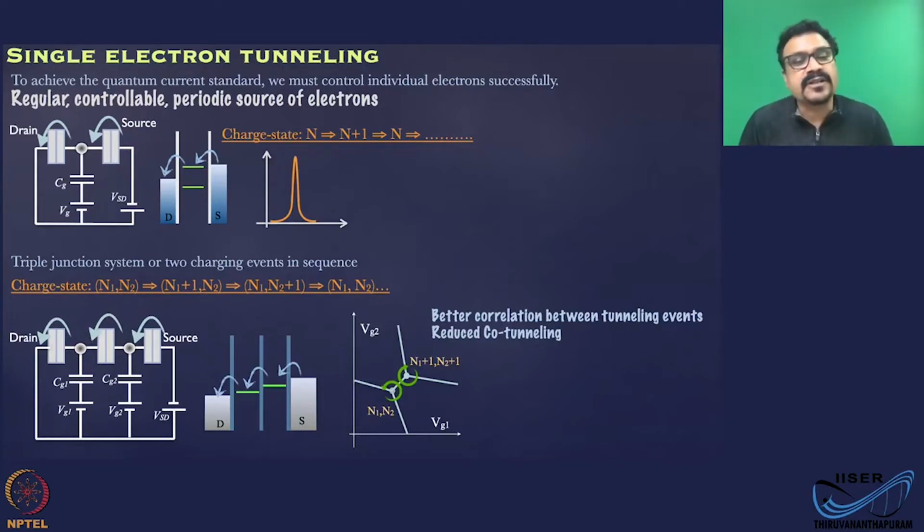So the tunneling of this electron from one dot to the other dot you can control very precisely in this situation. You can make each individual dot on or off the triple point, and you can control the sequential tunneling of electrons in a periodic manner just by using gate voltage pulses. That is the technology of the single electron pump.